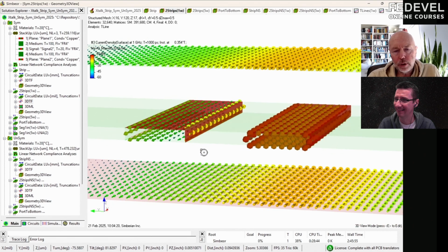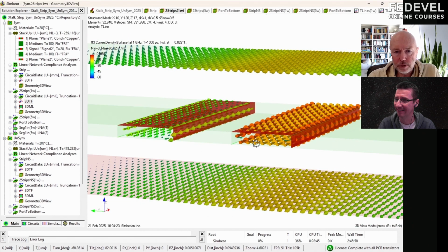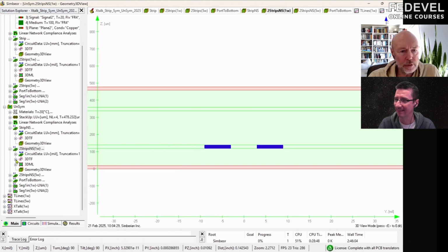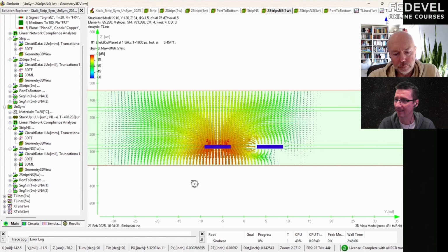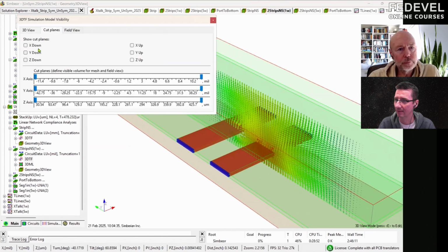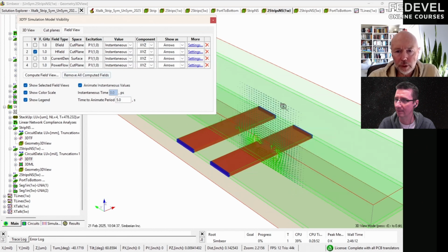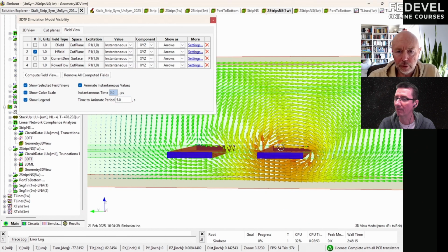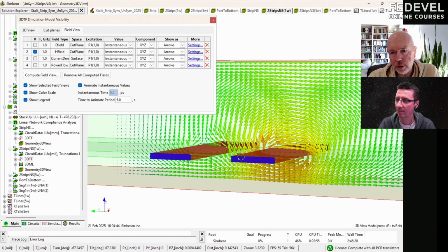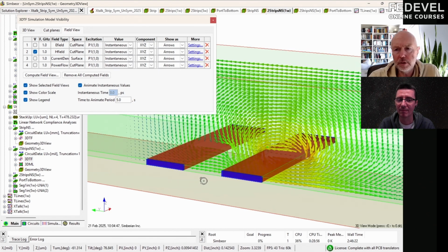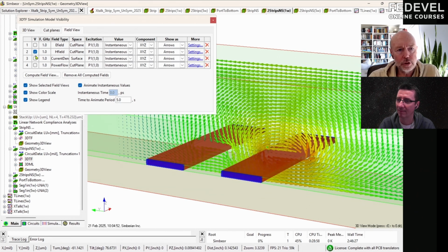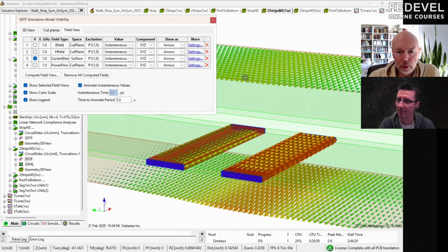So far-end crosstalk is pretty much cancelled in this case, but in case of asymmetric stack up, we can see, let's see, magnetic field. Magnetic field now is not symmetrical around. You can see this. And essentially this proximity, like some people call it proximity, but this is basically current distribution, all about current distribution. It creates this more far-end crosstalk.